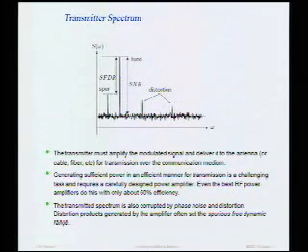Well, as we'll learn in this class, distortion is not only generated at harmonic frequencies, but intermodulation, cross-modulation distortion is also created at our own frequency. So if the PA is very nonlinear, it will generate distortion in band, which will actually corrupt the signal that you're transmitting. And we'll learn how that happens later on in the course.